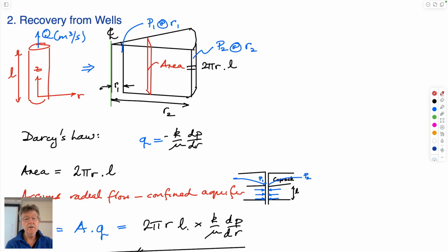And so we can calculate the rates at which we can recover fluid by looking at the recovery from individual wells. Water will be supplied. These wells are typically of the order of 4 to 8 inches in diameter, typically larger diameter than petroleum wells, because you need to get more volume or mass of fluid out of the ground because its energy density is much less. So if you go by value, a current barrel of oil is 120 and rising.